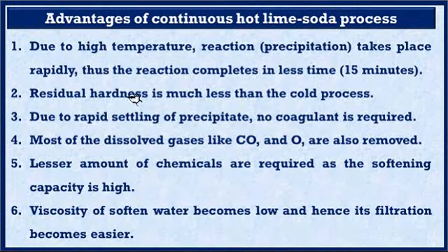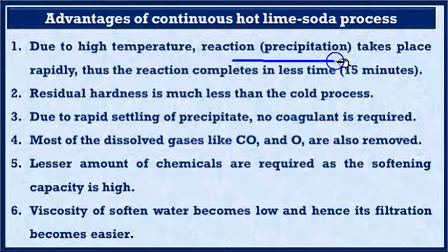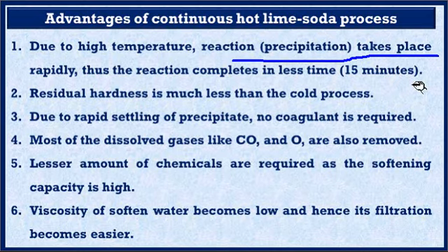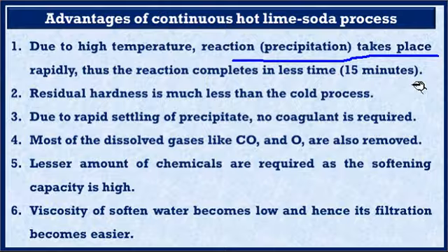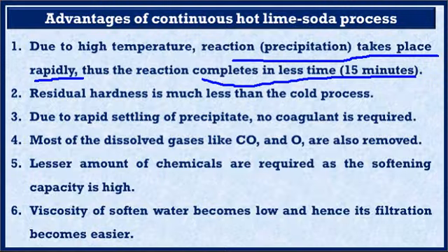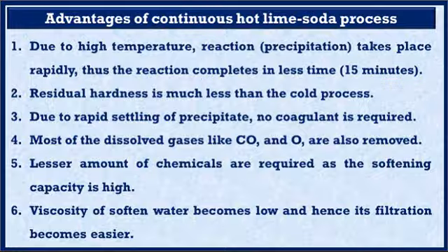Due to high temperature, the precipitation reactions of lime and soda with the hardness causing salts, and precipitation of these hardness causing salts, take place rapidly. Thus the reaction completes in much less time. Only in 15 minutes the reaction gets completed.